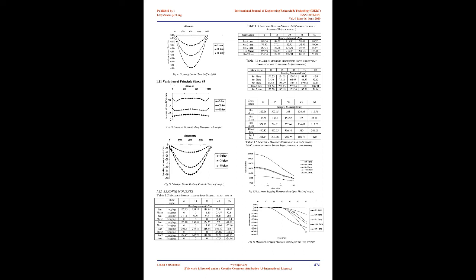1.8 Maximum bending stresses. The results for the normal right bridges were checked and matched with the conventional analysis. The following 3 cases were used for the analysis. A. Self-weight. B. Self-weight and symmetric live loading with respect to the longitudinal axis. C. Self-weight and eccentric live loading with respect to the longitudinal axis. For convenience, the slab has been divided into 5 zones and the maximum stresses developed in those sectors were tabulated, and as the stresses in the top and bottom surfaces were equal they were easily converted into bending moments.